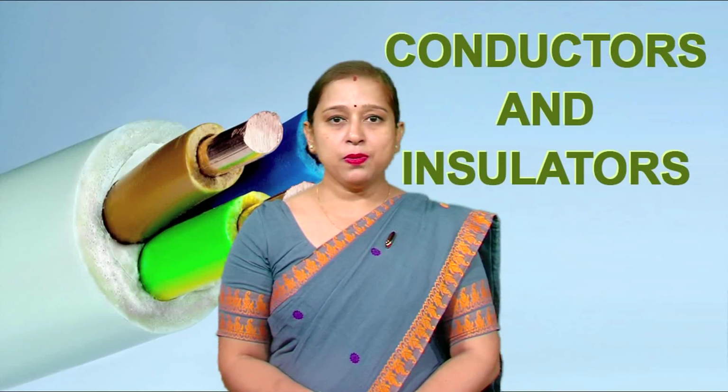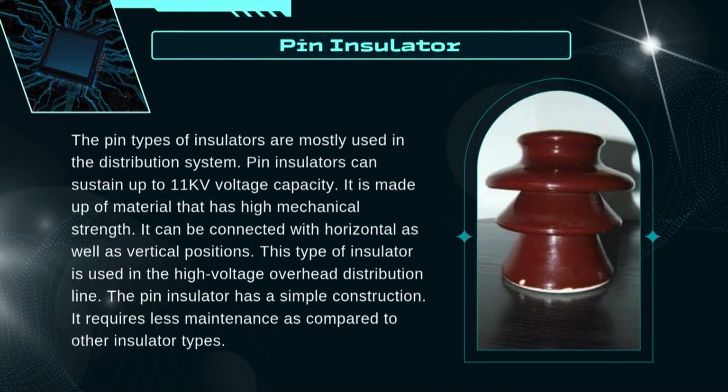So in case of pin insulator, the pin type of insulators are mostly used in the distribution system. Pin insulators can sustain up to 11 kV voltage capacity. It is made up of material that has high mechanical strength. It can be connected in horizontal as well as vertical positions. This type of insulator is used in the high voltage overhead distribution line.